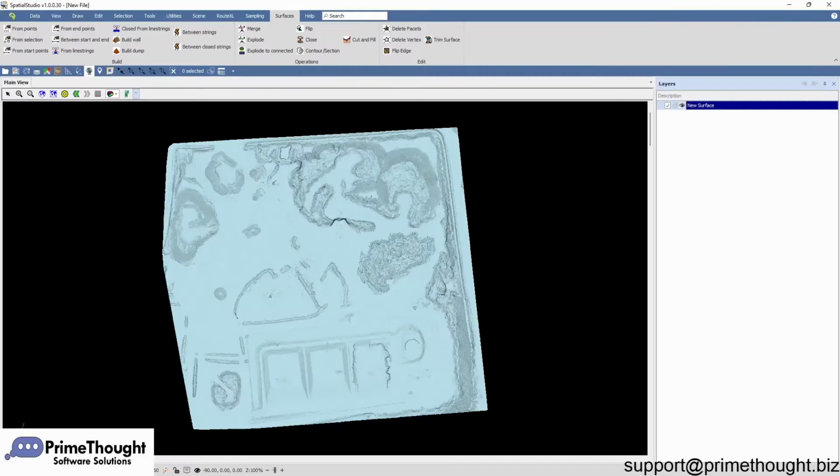In this video, we will go over how to get section views in our spatial products. This allows you to view sections of surfaces when working in 3D and move through these sections bit by bit. A view depth can be set that allows you to view only a certain distance into the surface at a time. A profile can then be gotten at various points along the surface.